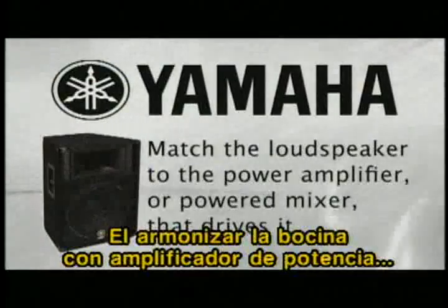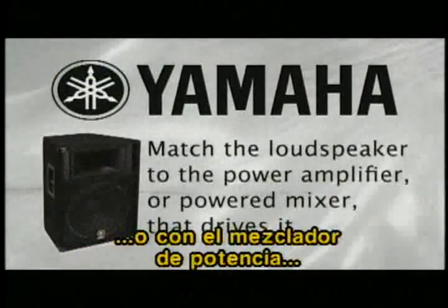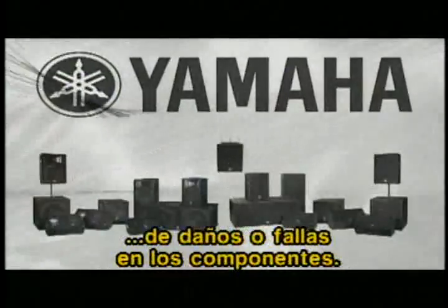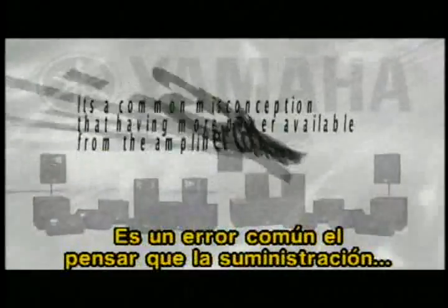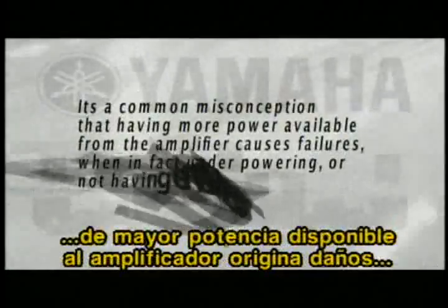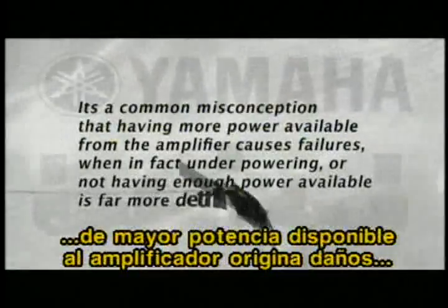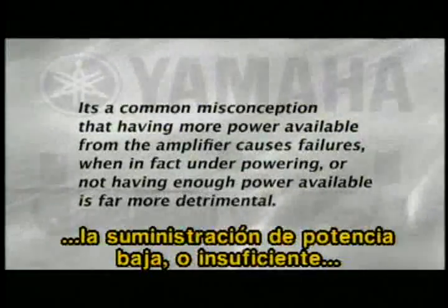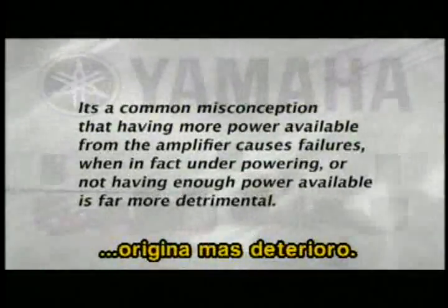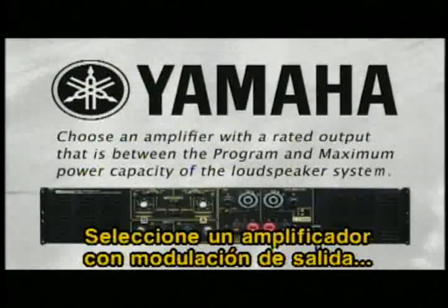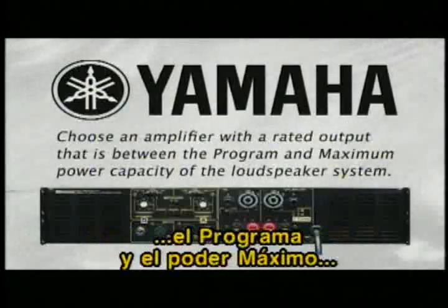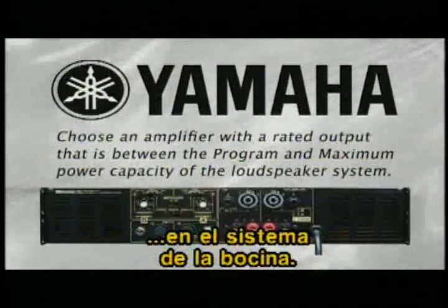Matching the loudspeaker to the power amplifier or powered mixer that drives it will help to reduce the chance of component damage or failure. It's a common misconception that having more power available from the amplifier causes failures, when in fact underpowering or not having enough power available is far more detrimental. Choose an amplifier with a rated output that is between the program and maximum power capacity of the loudspeaker system.